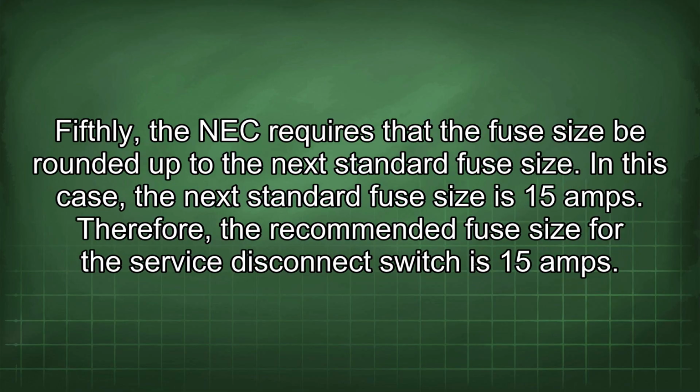Fifthly, the NEC requires that the fuse size be rounded up to the next standard fuse size. In this case, the next standard fuse size is 15 amps. Therefore, the recommended fuse size for the service disconnect switch is 15 amps.